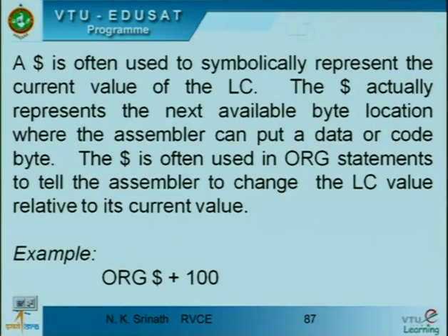A dollar is often used to symbolically represent the current value of the location counter. The dollar actually represents the next available byte location where the assembler can put the data or code bytes. The dollar is often used in an ORG statement to tell the assembler to change the location counter value to its new value.